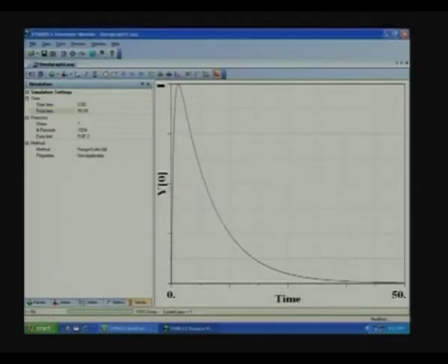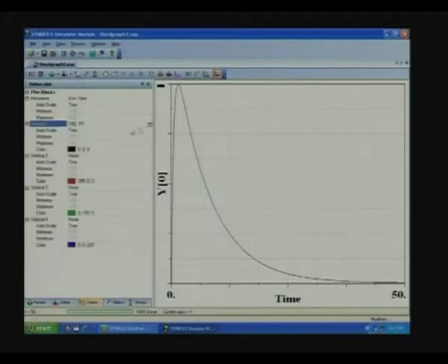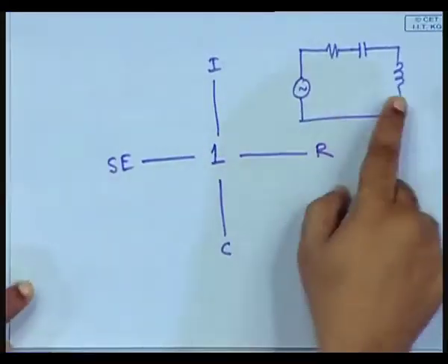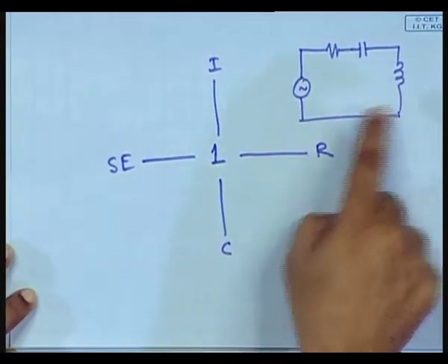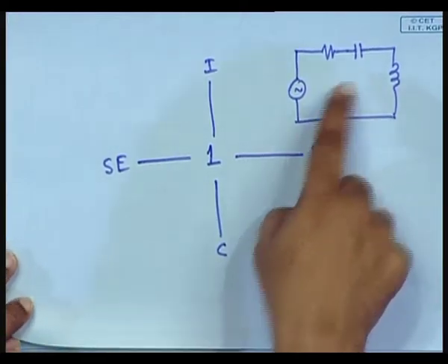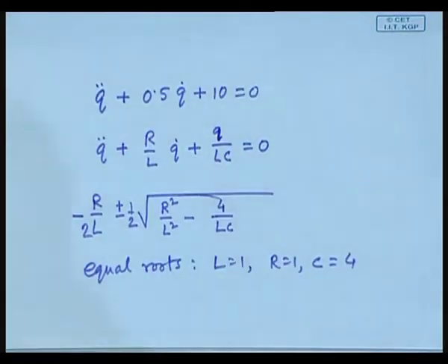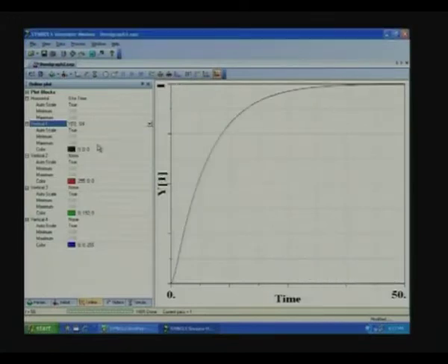Okay. So, it goes and then it decays. Now, what did I plot this time? I plotted time and P2. P2 is the current through the inductor. Notice the circuit, the current through the inductor, because of the capacitor, must go to 0. So, it goes up and goes to 0, but what is the capacitor voltage? That will stabilize to some other value. So, if I plot something else, say Q4, it is stabilized there. Fine. But this is an overdamped system.